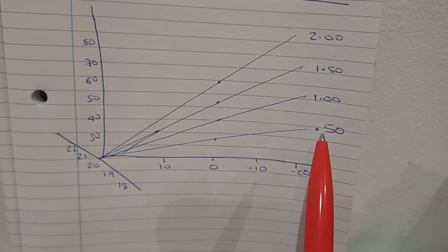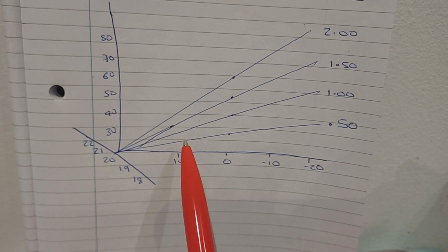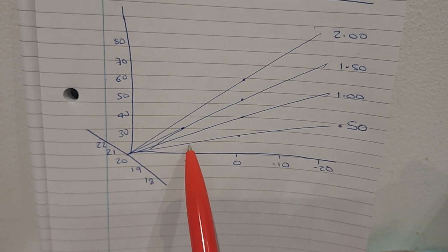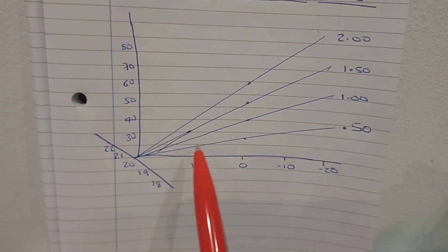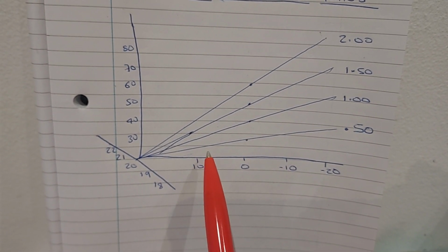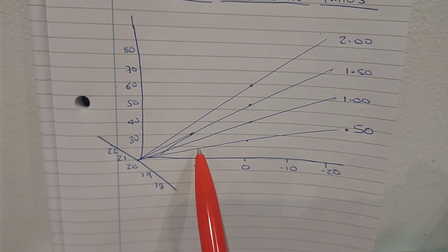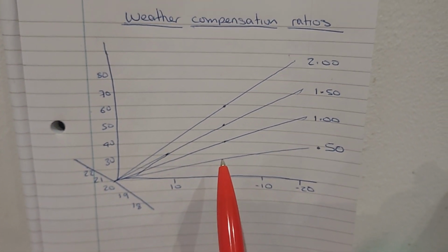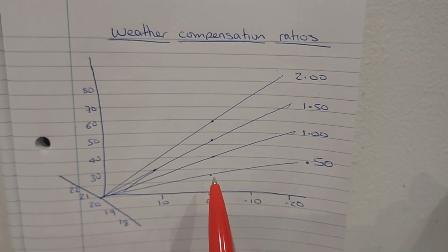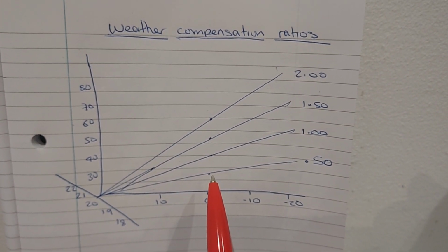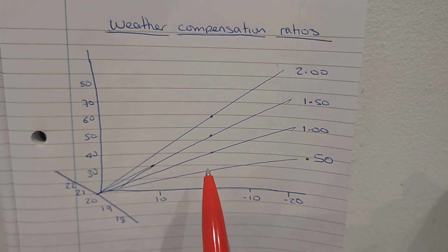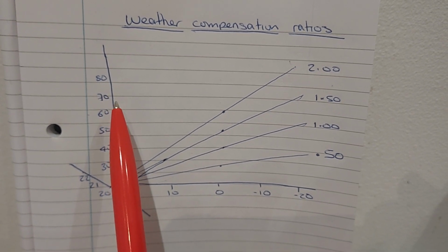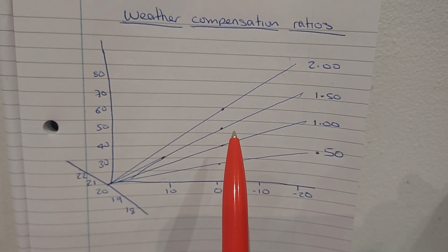And there again, if we were doing underfloor heating, we'd have a curve of 0.5, and that would mean that, so we dropped 10, so we'd expect to see 5 degrees plus our 20, so a flow temperature of 25 on our underfloor when it is 10 degrees outside. Now at 0, we would expect a flow temperature of 30 for an underfloor heating system. And this is where you hear me talking about low temperature underfloor heating. Most underfloor heating systems are set to run around 50. The water's supplied up about 70, gets blended down to 50, and they're operating here.